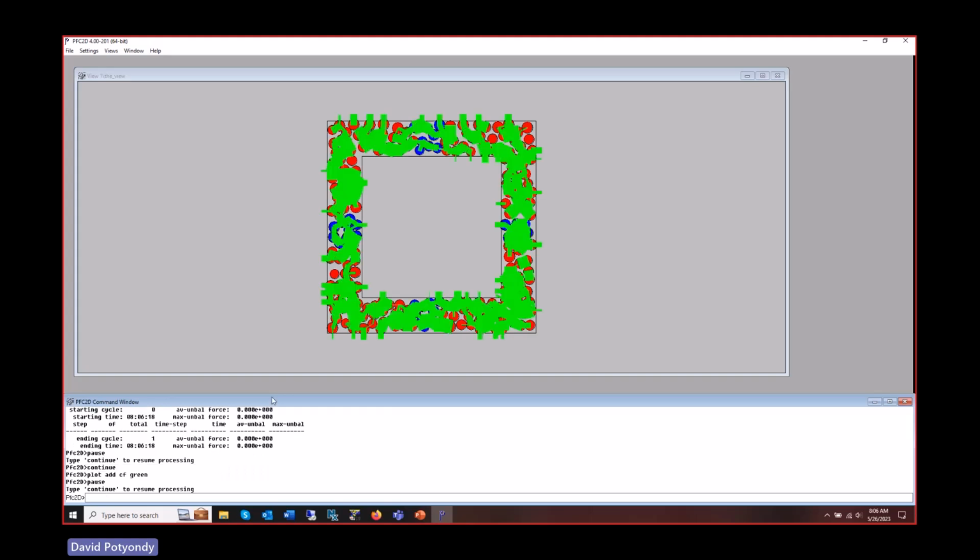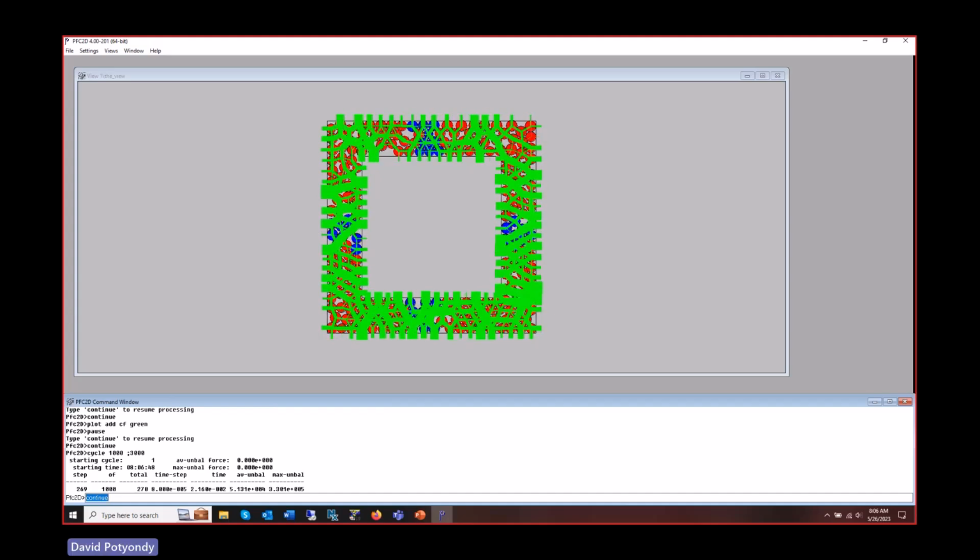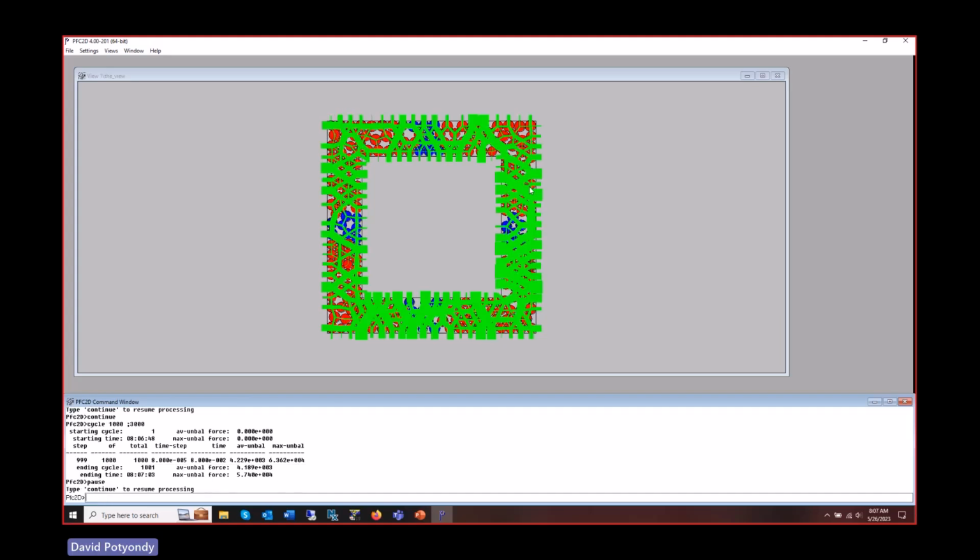So there we go. Those are the current force chains. We're drawing black, green is now compression. Those are the force chains, big, high, crazy force chains because of high, crazy overlaps. Now everybody's frictionless, so you can see the system readjusting itself, and there are still a few rearrangements occurring. We're going to take 1,000 steps and say we're close enough. We're not 100% in static equilibrium, but close enough. It's packed tighter here than over here, right? Higher values, thicker lines. Look at these guys. They're kind of shielded by the big high compression chain over here.